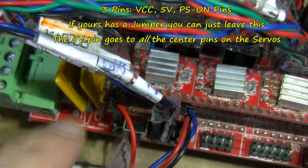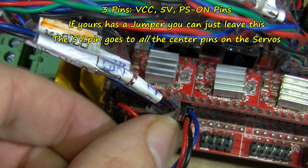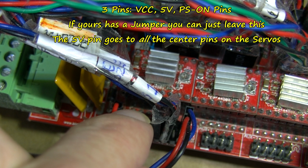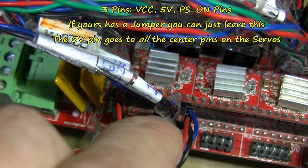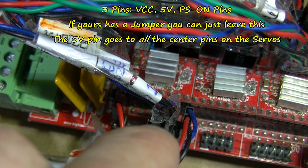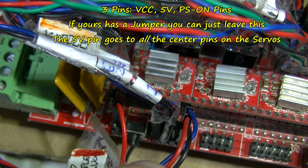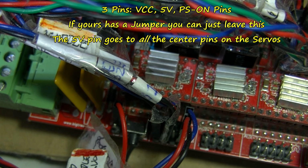Now in my case, as I say, I've got 5 volts coming in here through that red wire, separate from the Arduino. That's to power the servos, because you need more amperage for the servos. And that power line, there's a circuit track going along here, going to all the servo pins, as I call them. Let me have a look at the, yes, it does say that on the printout. I have the wiring printout.